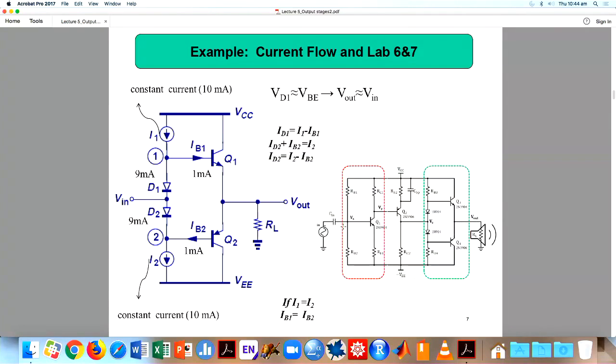And then this is a common emitter amplifier. So this is called a push-pull stage. The push-pull stage is used in the output stage to push up your current or enhance the power, especially when you need lots of current at the output. That's the reason in the operational amplifier they have got an output stage. That output stage is to increase the current, because you amplify the voltage in the multiple stages. Then in the last stage they amplify the current. So that's called the output stage. And in the operational amplifier, in all the amplifiers, the output stage is the last stage.